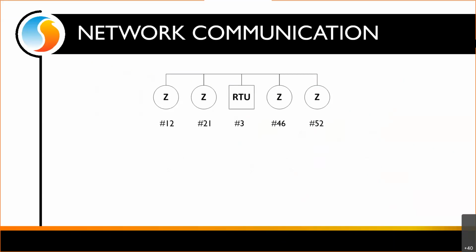So if ever you have a building where maybe we have an air handler or a rooftop and it's centered in the middle of the building and you've got some zones going to one side and you've got another set of zones going to another side, you don't have to do the daisy chain where the rooftop is at one end. But generally, we want the daisy chain to take the shortest path possible. So in that case, it would be advantageous to be able to network the rooftop controller in the middle so that we don't have to loop over it again in case it is at one end.